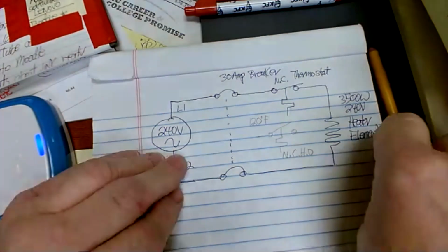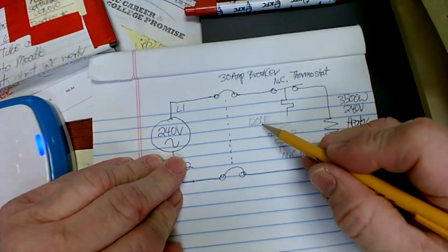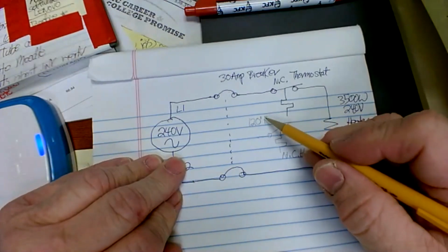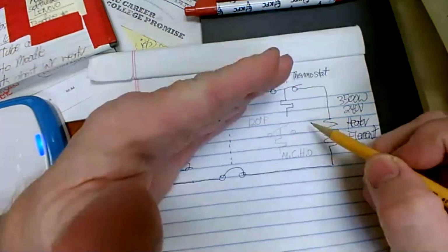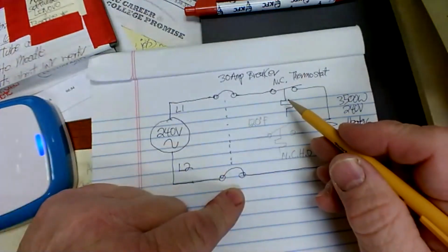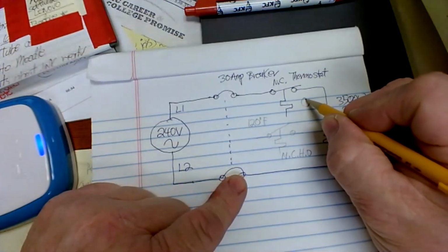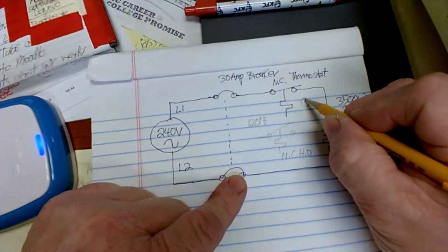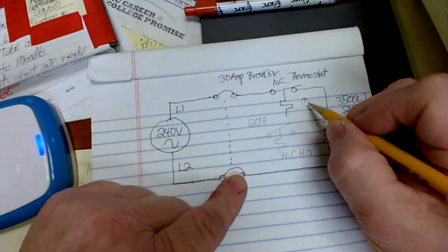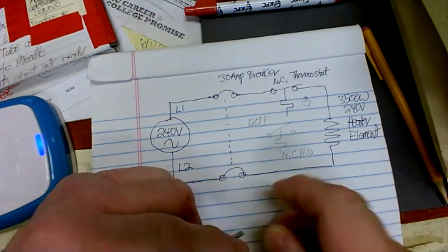Okay. So it's run completely based on if you're at the 120 degrees Fahrenheit or whatever you got it set for. If you are, it opens, and if you're below it, it closes, and it lets you heat. So that's how it regulates. And there'll be a dial setting on this thing. There'll be like a dial, a pointer, that you can adjust possibly with a screwdriver.